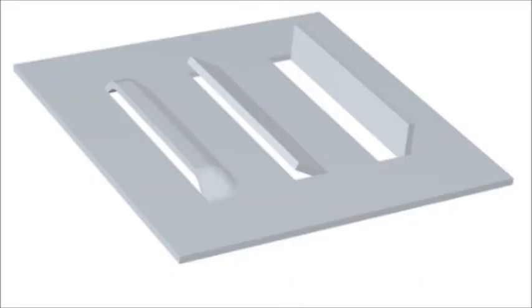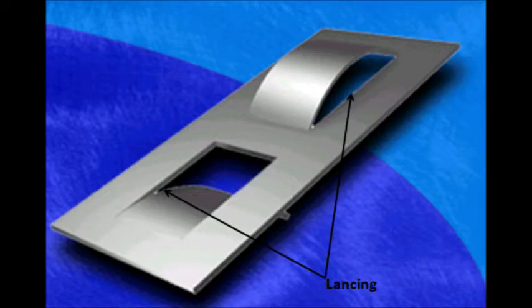Next is lancing. Lancing is an operation in which the workpiece is clipped and bent in one swift motion without the reduction of the material. Instead, it modifies the workpiece configuration. One side of it remains connected to be bent rather than having a closed shape.